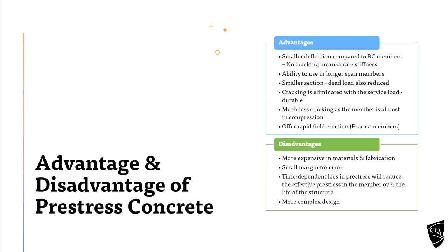So that gives some advantages and disadvantages. That is the concept we are going to use. We apply some pre-stress force in the tension zone, so that it reduces the deflection, so that the tensile stress will be less, so that the cracking will be eliminated.